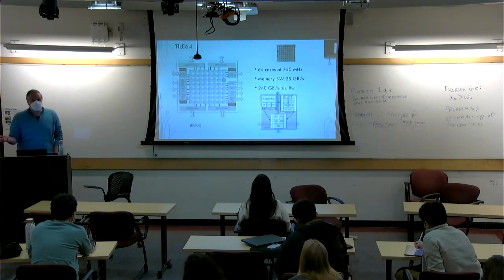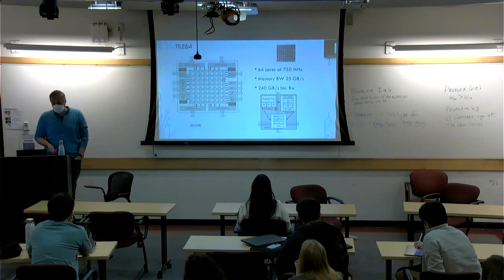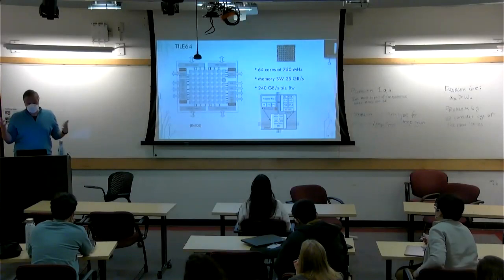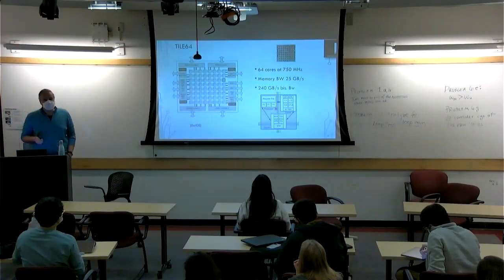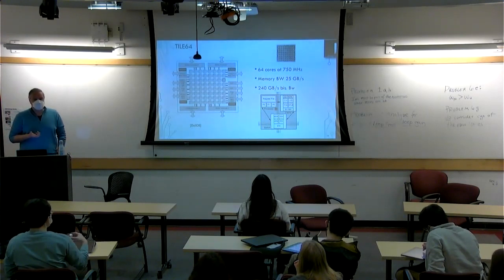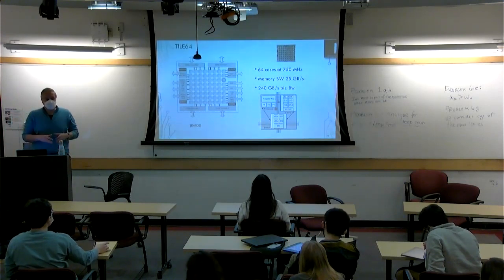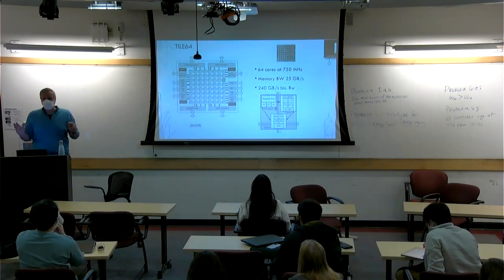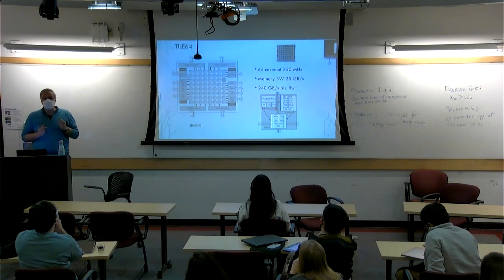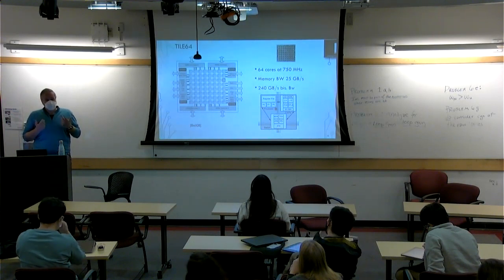Okay, I mentioned Tile64 a few times. This was one of the early examples of a relatively large 64-core ASIC. And the interesting thing here, historically, is that it was a simple network, 5-port routers, full mesh. It was actually 5 different meshes on top of one another, each dealing with a different architectural or application requirement.